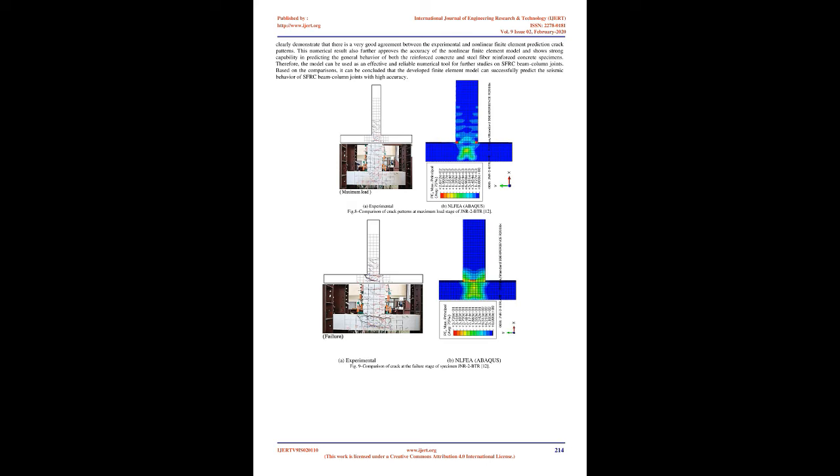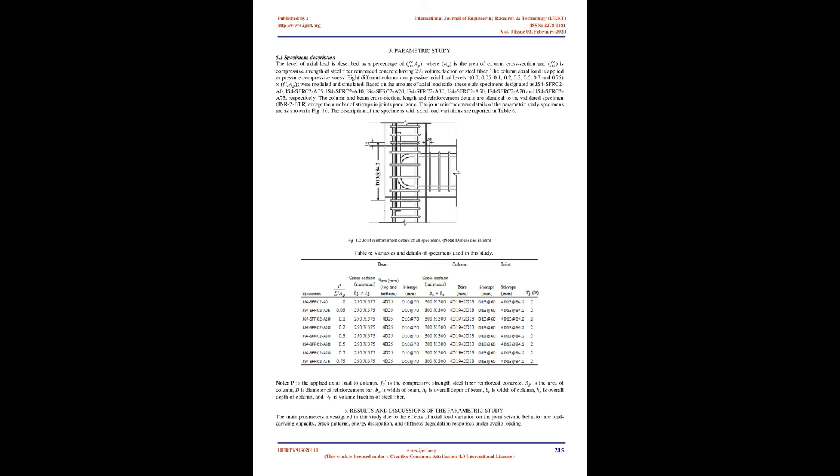The tensile stress-strain behavior of reinforcing bars was assumed to be elastic with corresponding Young's modulus and Poisson's ratio. The nonlinear behavior of steel bars was modeled as a bilinear elastic-plastic material using a strain hardening ratio of 0.01, as recommended by Kishlakov and Miller [47], and it is used by many researchers [48, 49]. The typical bilinear stress-strain model of reinforcement bars is shown in Fig. 4.